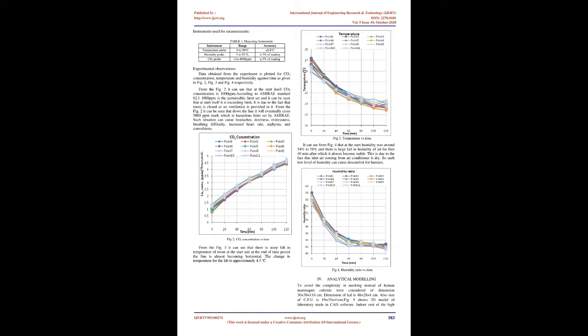Merve Kuru et al., 2018, studied thermal comfort parameters and CO2 concentrations in a university classroom, which were gathered via field measurements, and occupants' sensation and perceptions were collected via subjective surveys. The PMV indices were calculated to assess the thermal comfort conditions of the classroom. They found that thermal sensation, relative humidity, and air velocity perception of occupants have a statistically significant effect on CO2 perceptions of occupants. The majority of CO2 concentration measurements exceeded the permissible concentration value of 1000 ppm stated by ASHRAE.